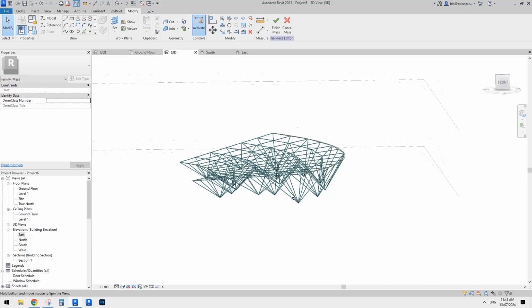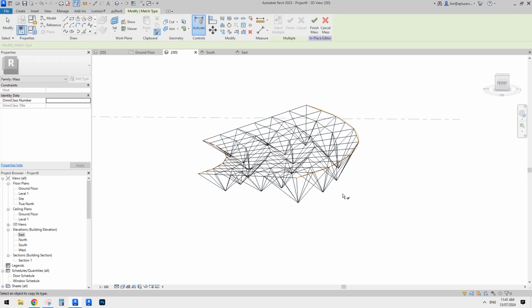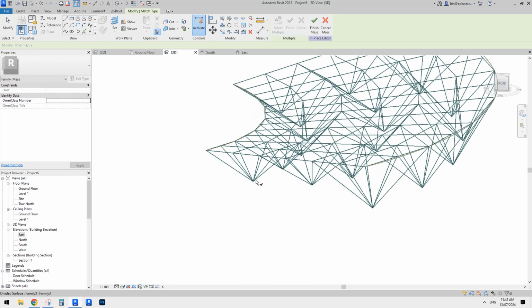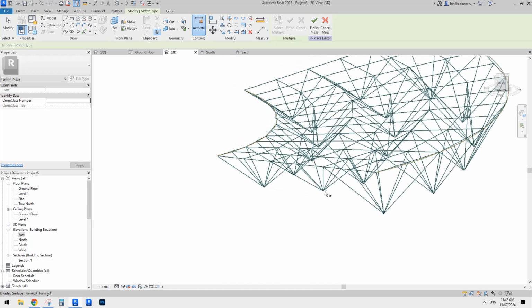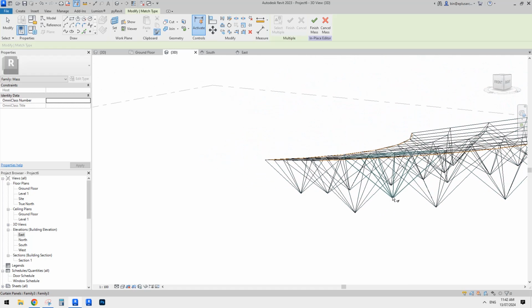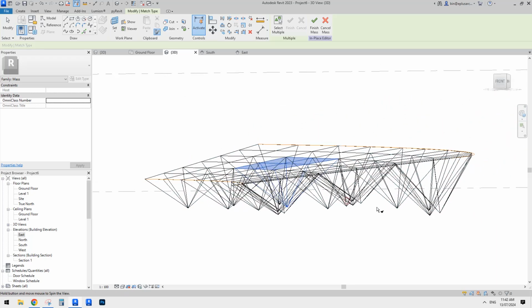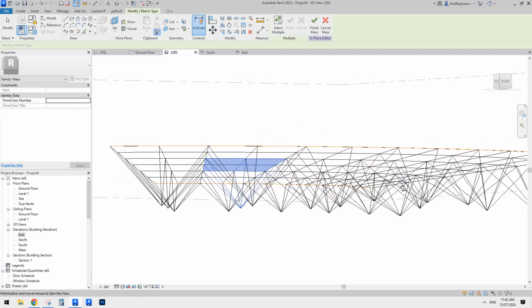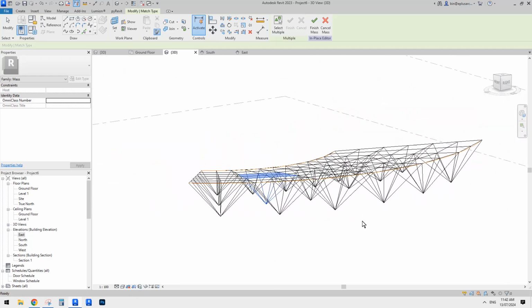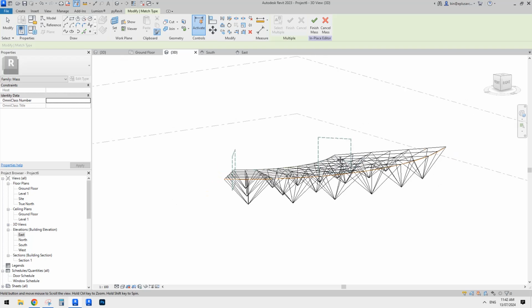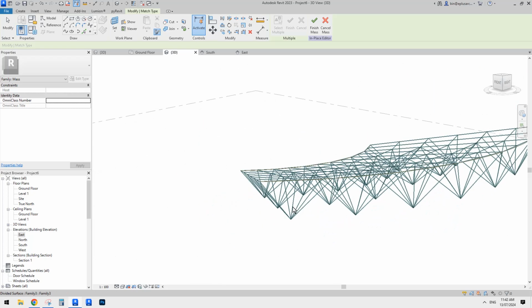Okay, so now let's do it again. MA, right? So you need two steps. One step is to pick the original one and then pick the next one. So tab, and you can continue matching, or do multiple matches, but if you click anywhere without picking anything, this will restart your match command, which means you can pick a new one.